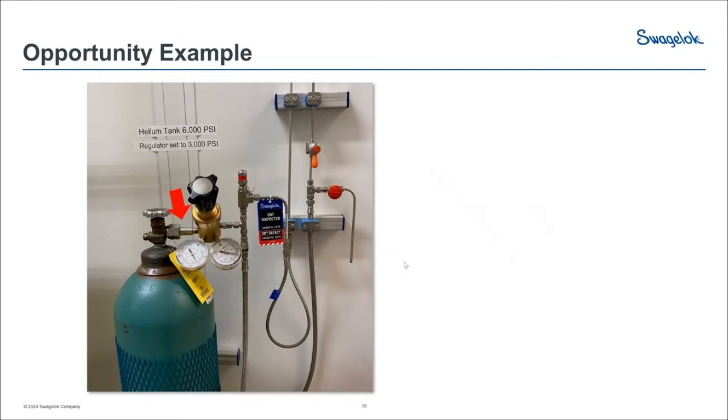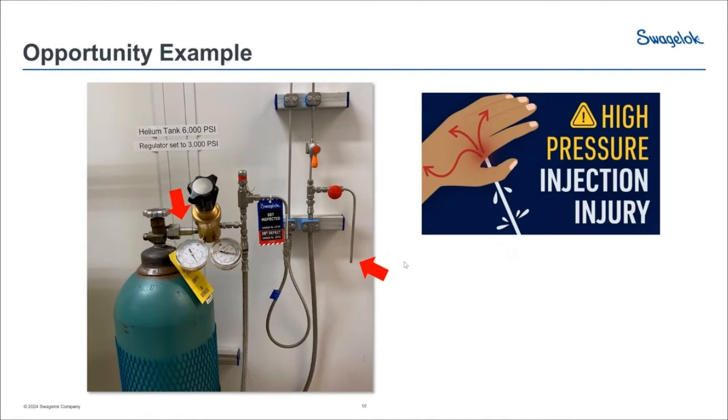The first thing that I see is a lack of adequate regulator creep prevention. Namely, there's no filter upstream of that regulator. And we're going to unpack this a little bit more in a moment. The second observation is really around a key safety insight.